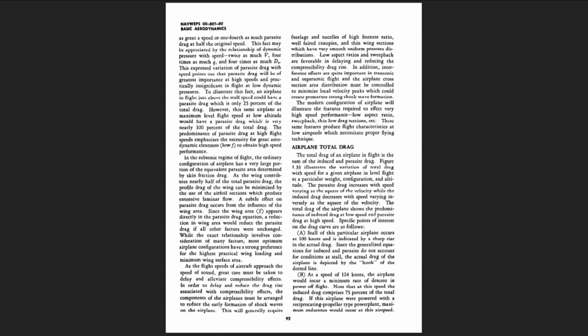The modern configuration of airplane will illustrate the features required to effect very high speed performance: low aspect ratio, sweepback, thin low drag sections, etc. These same features produce flight characteristics at low airspeeds which necessitate proper flying technique.